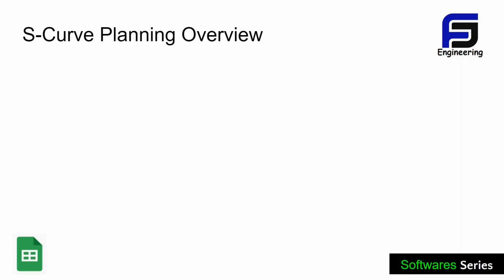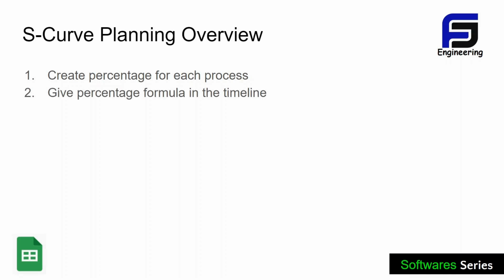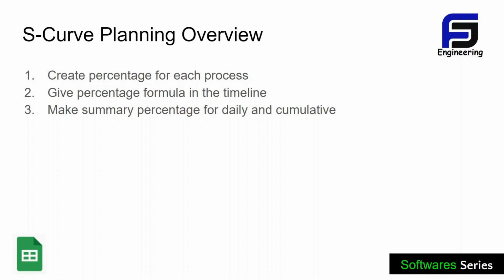Well, here is the overview, or step-by-step, to create S-curve planning. First of all, we will create the percentage for each process. After that, we will give the value in each process in the timeline to get the percentage. Then we'll make a summary for each timeline to get the daily percentage and cumulative percentage. Lastly, we will create the graph or S-curve.